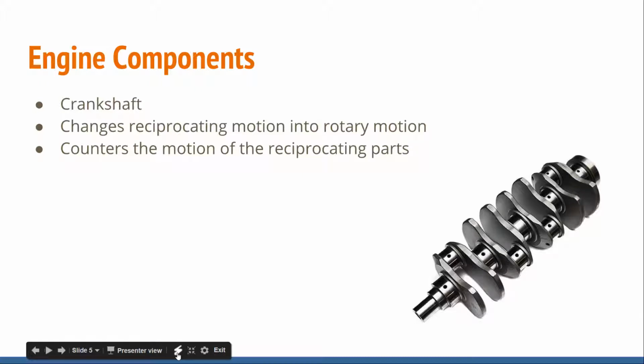It balances it. It basically has the weights on the bottom of it to smooth out an engine that's going to be running. Without those weights, it's just going to be a vibrator, and the thing's just going to basically rattle itself apart. So another job that the crankshaft has is it adds momentum. It adds momentum to the engine, helps everything keep spinning in the right direction, and keeps it from stalling out.